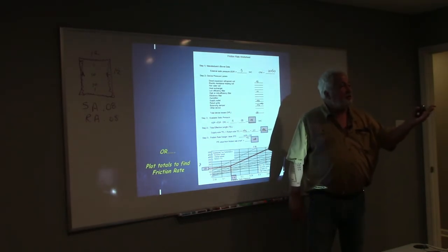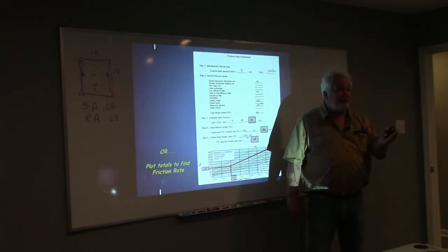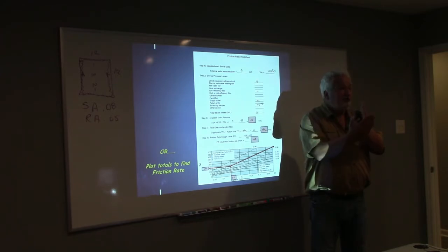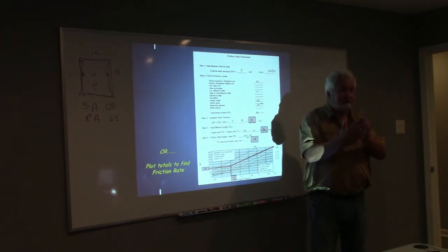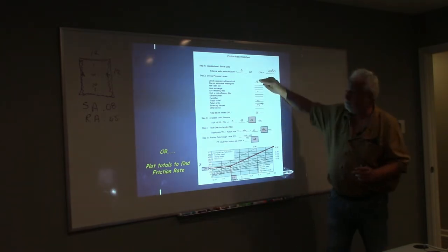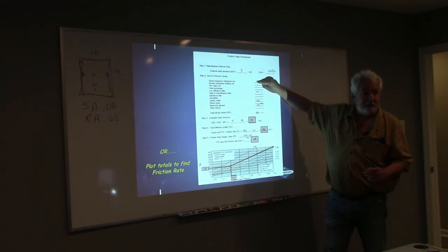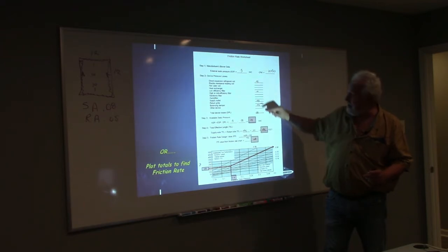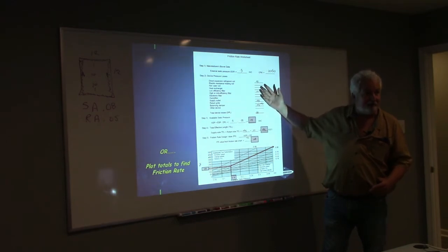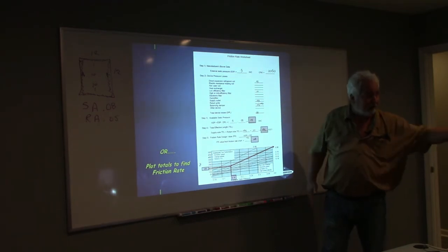The 0.1 came from back when we had coils you could read a newspaper through. So how much resistance is that? Very little. As the coils got more restrictive, I had to make the ductwork larger because the blower was still only going to move X amount of air. So that's where that 0.1 came from.